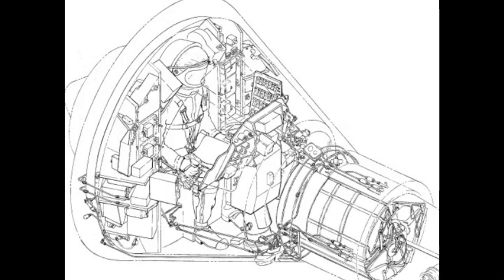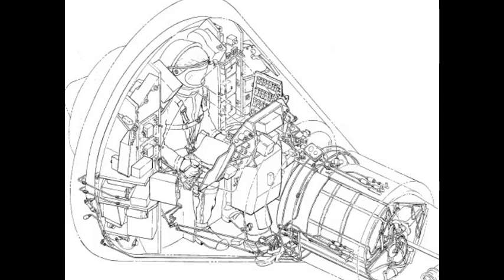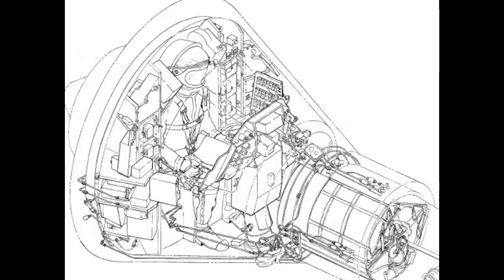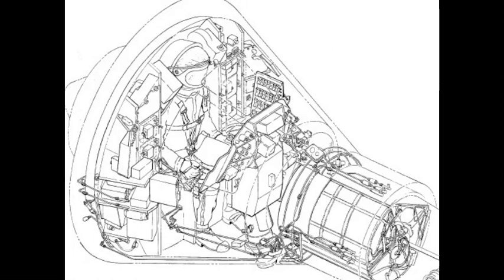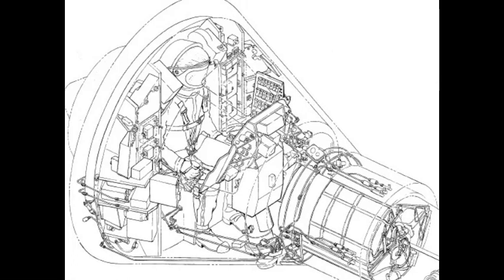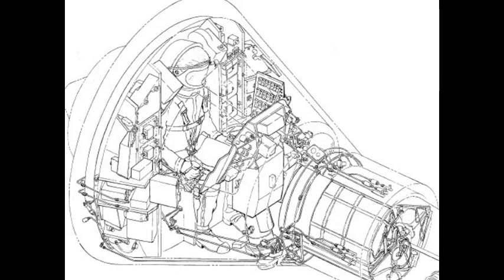The aft end of the conical section adjoins the recovery system compartment. The forward end of the conical section is attached to the forebody heat shield. The combination of the conical section beaded outer skin, the hat section reinforcements, thermoflex insulation, and external shingle installation provide the capsule with adequate heat, noise, and meteorite penetration protection.